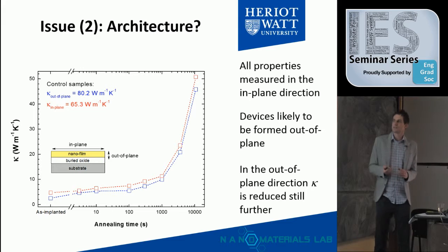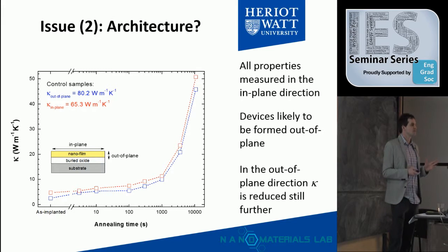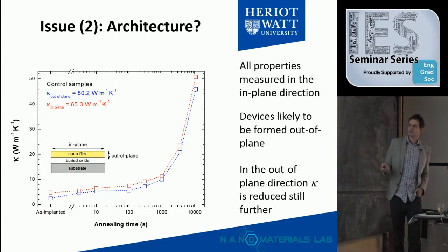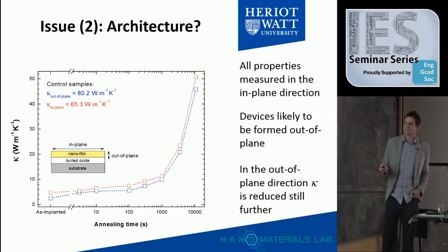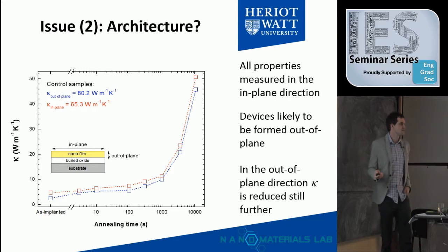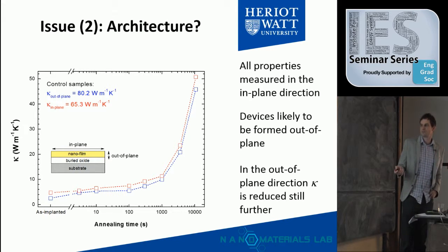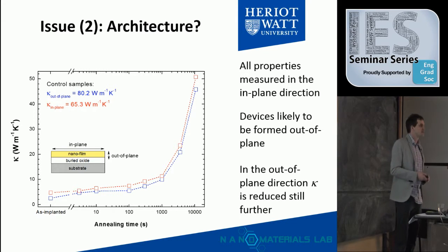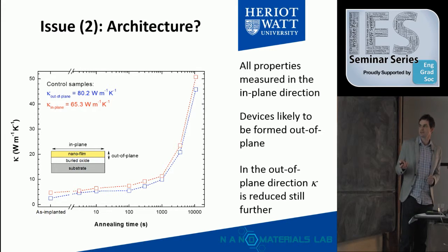The other issue I would say as well is we've so far looked at our properties in the in-plane direction, so measuring through the length of the film. Usually the devices are made in the through-plane direction. We've done some measurements as well, looking at the differences in the thermal conductivity in the two directions, and they're not much different. If anything, we do see slightly better values in the out-of-plane direction as well. So we don't think that will be an issue particularly.